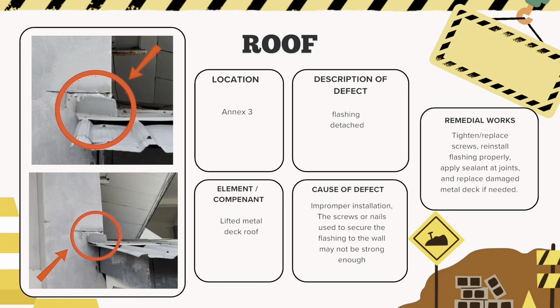Lastly, for the remedial work, the recommended action is to tighten or replace screws, reinstall flashing properly, apply sealant at joints, and replace damaged metal deck if needed.